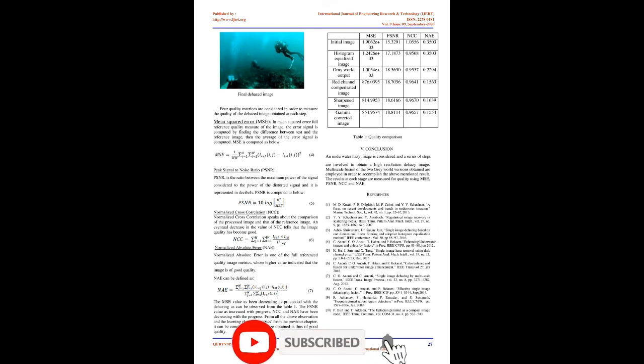Multiscale fusion of the constructed Laplacian pyramid of the sharpened image and the Gaussian pyramid of the gamma corrected image is obtained. Thus, a de-hazed high-resolution underwater image is obtained. The MSE, mean squared error, PSNR, peak signal-to-noise ratio, NCC, normalized cross correlation, and NAE, normalized absolute error, are measured at each level of de-hazing. Thus, the results are compared.